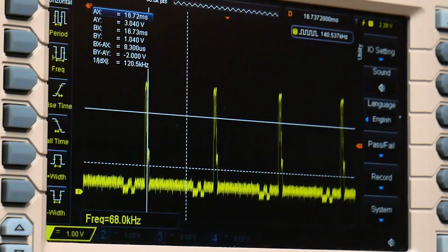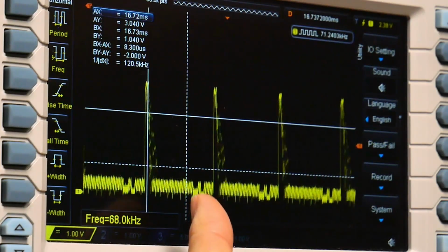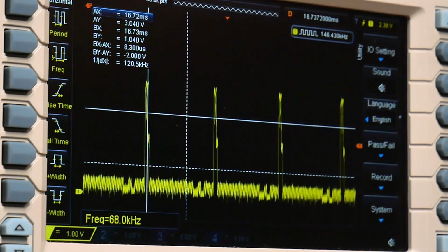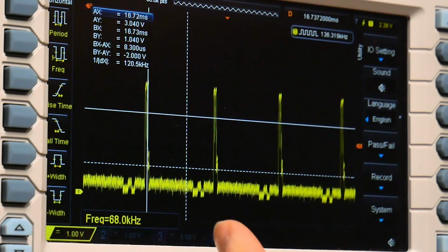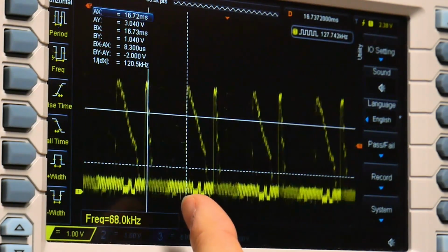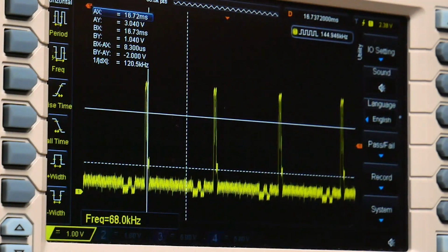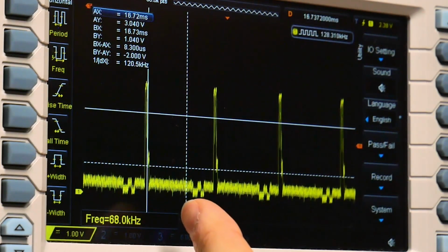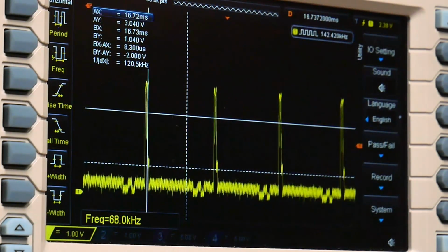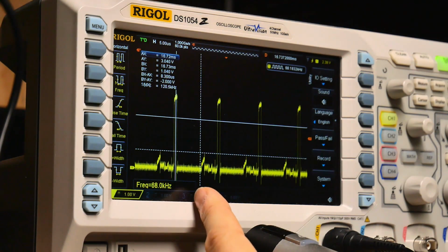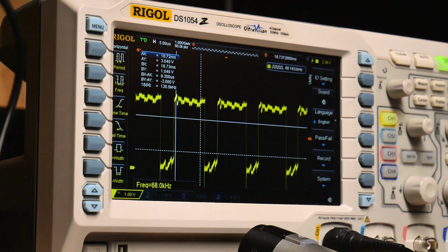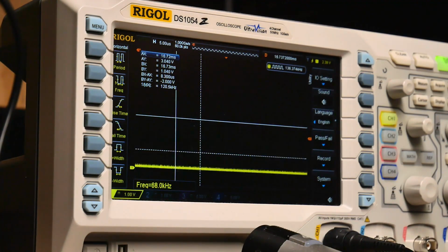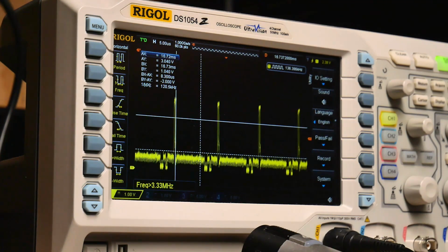Okay, so the RAMs are out, but the LS245, 244, and 373 are in. And what the heck is going on there? I'm not moving the oscilloscope probe around. It's just stuck in one of the pin sockets. And what is going on here? That's just screwed up. This cannot be right. There's no way that this behavior is correct. It should be rock steady, just like this signal right here. Or this one. Even though it's got some bumps on the top and bottom, this is okay. That's not bad. And when I turn the computer off and back on, look, it's sort of all over the place.